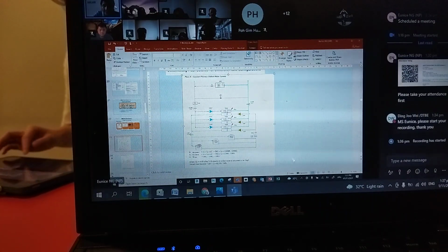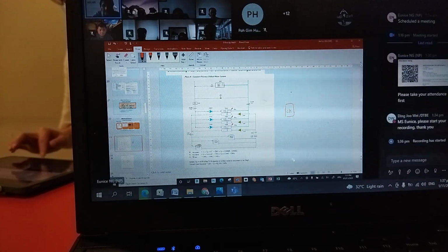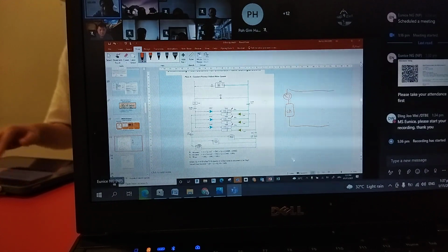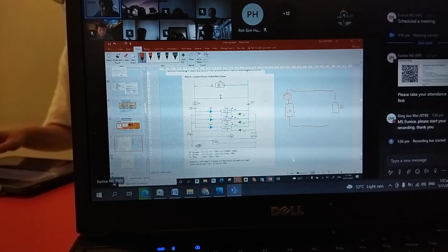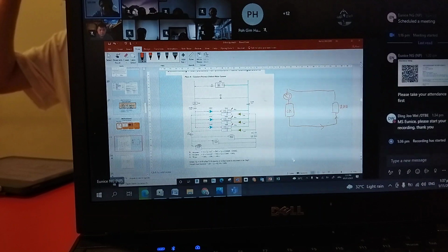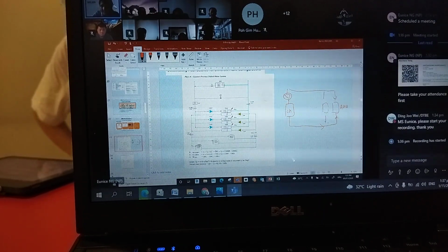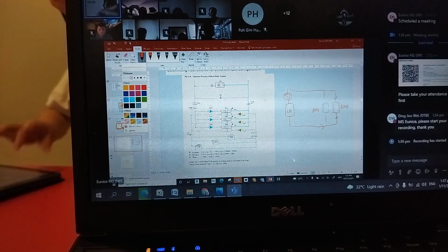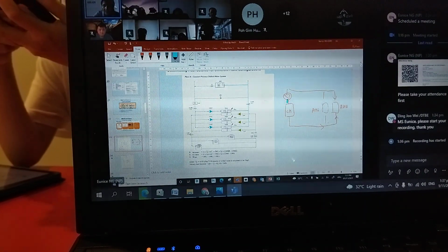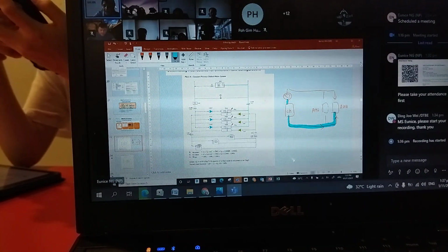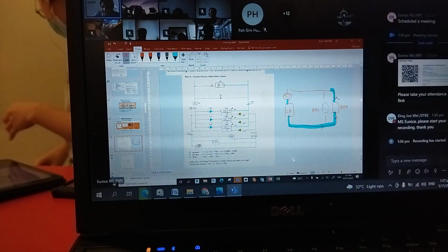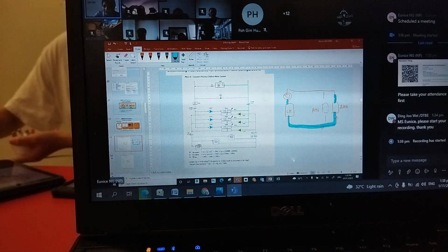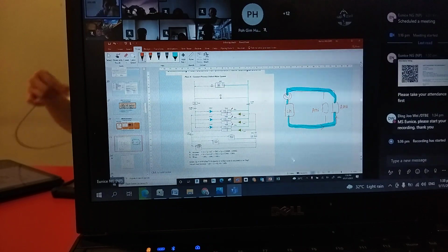So I have a pump. This is my chiller, so the pump is pumping to the chiller, then all the way to the loop, AHU. Water goes to the AHU. Now there are a lot of AHUs. So this pump, that pumps the chill water, must meet the critical path. Oh sorry, this is the wrong side. It must meet the critical path, meaning the path that has the highest resistance.